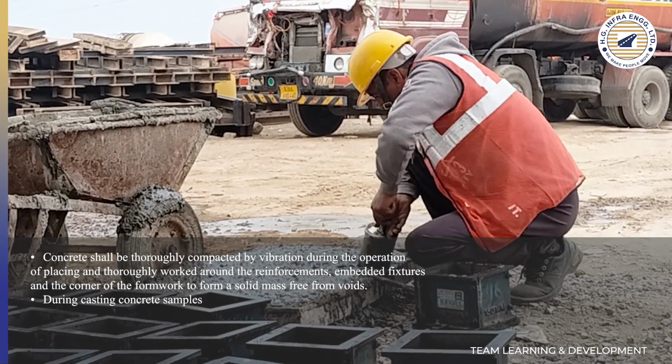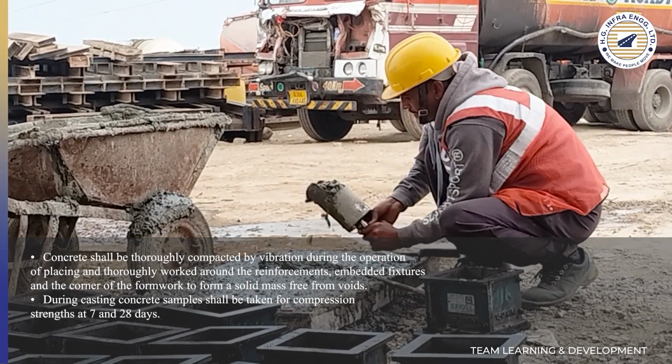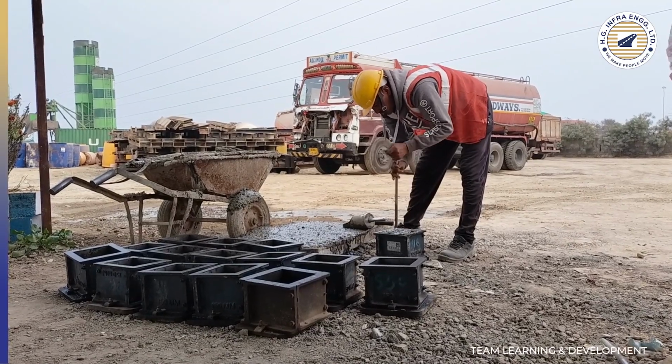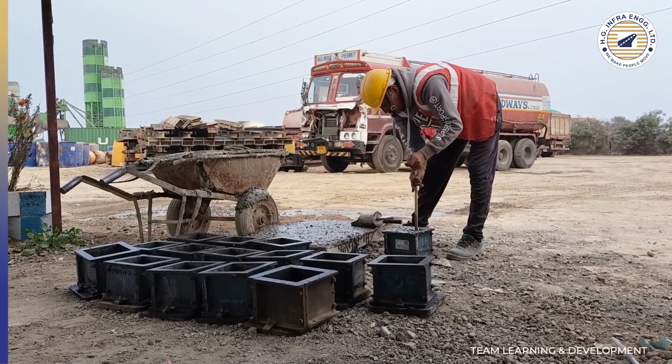During casting, concrete samples shall be taken for compressive strengths at 7 and 28 days. The number of samples will depend on the quantity poured and will be governed by IS 456.